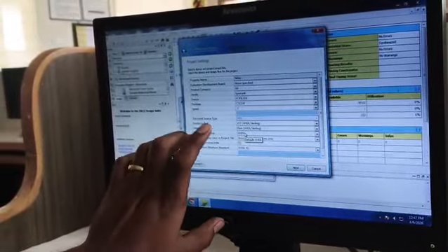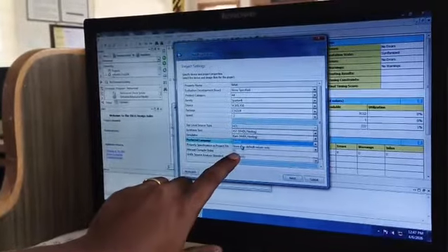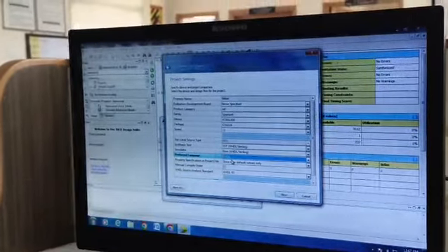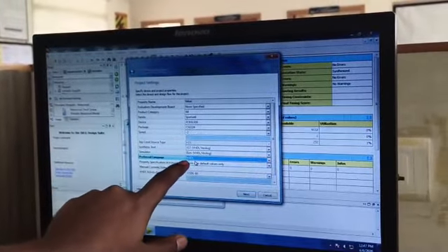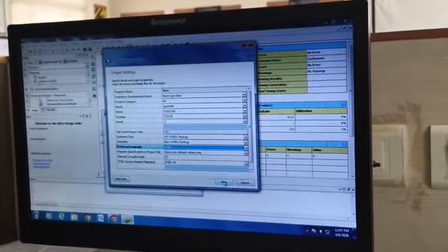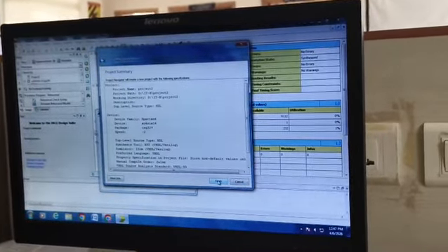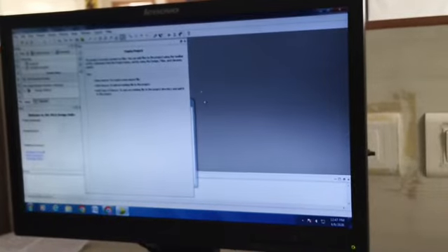We are going to do VHDL programs, and in some cases Verilog has been selected, so now we need VHDL. Ensure these three options, then select Next and Finish.